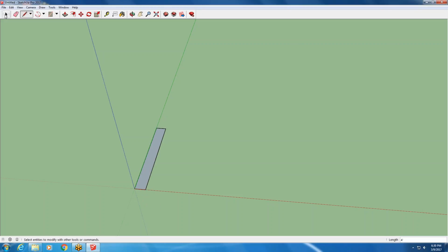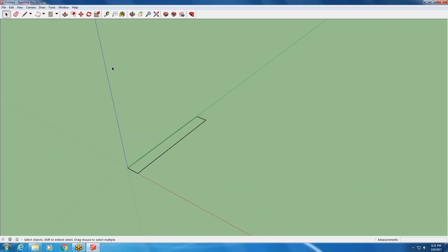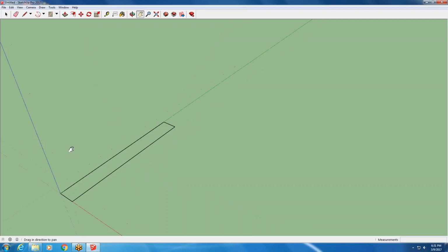If you were to do something a little different, instead of deleting one of the edges, you were in fact going to delete a face, the same problem stands. You have effectively cut open the loop. Even though you can see these 4 edges, SketchUp doesn't know that you have a closed loop anymore because you've deleted the face that ties them together. In order to fix your mistake, you simply need to pick a side to close off again and close the loop. Are there any questions at this point?